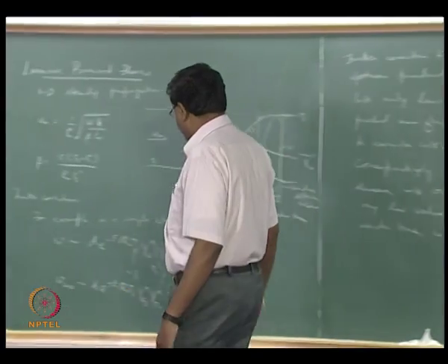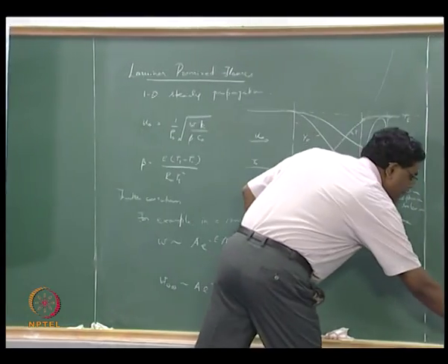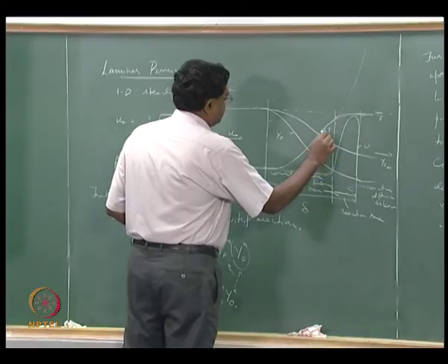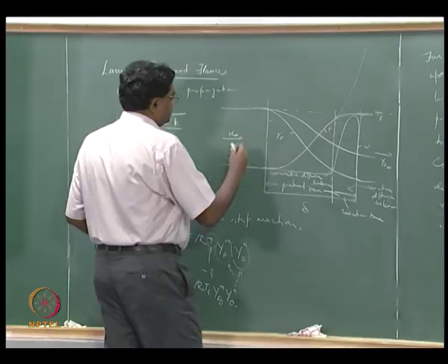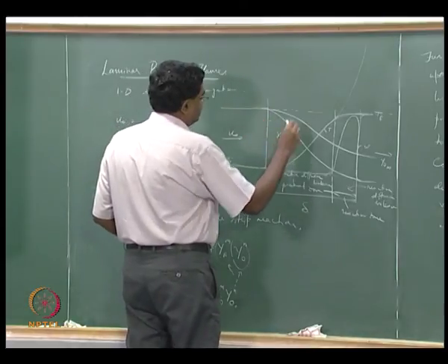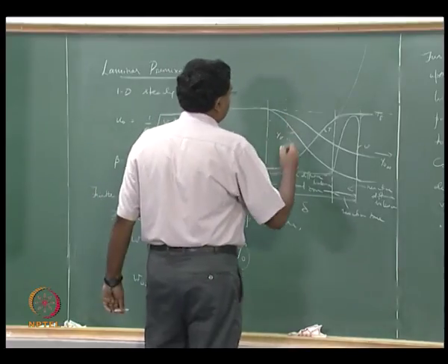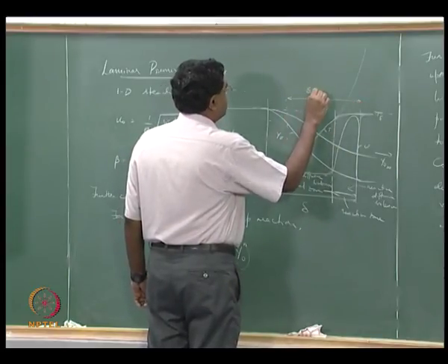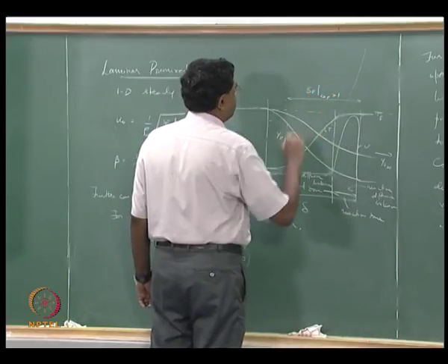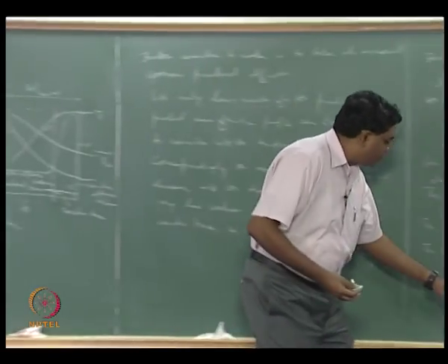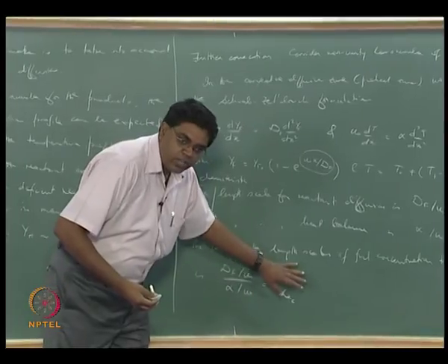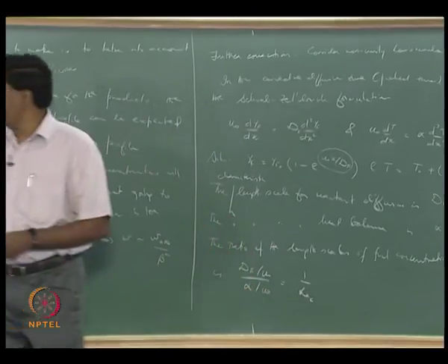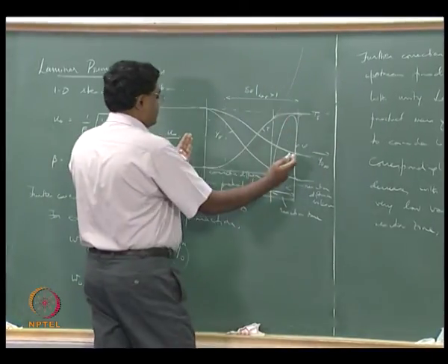That means if I go back and use a different color chalk piece and say forget about that, that's an X species. So what you are talking about is we are saying that this length scale for the species is now going to be delta F, with LEF greater than 1. If I had a Lewis number for the fuel greater than 1, then 1 over something greater than 1 is less than 1, therefore df over u naught is less than alpha over u naught, and therefore this distance should actually be less than that distance.